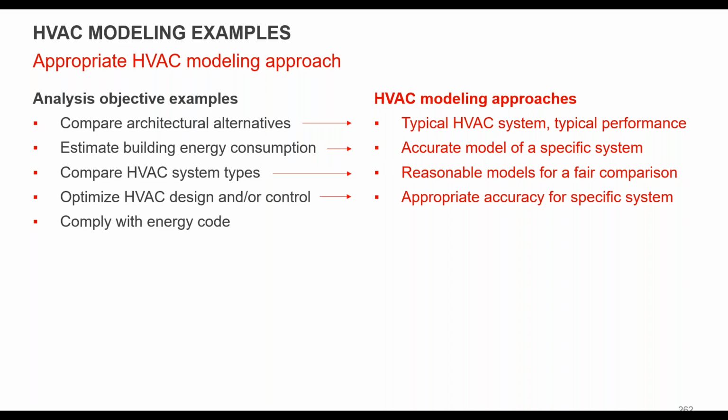If you're optimizing actual specific control sequences, then yes, you're going to be spending a lot of time making sure that your fan controllers are set up correctly. If you have resets in place or static pressure resets, that they're operating as intended. You're going to be looking at hourly data, right? So you're going to be making sure that those are very tight.